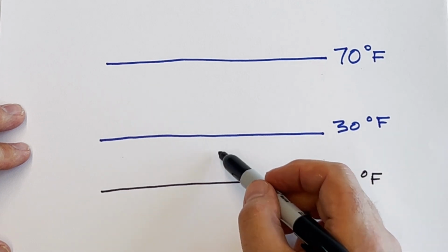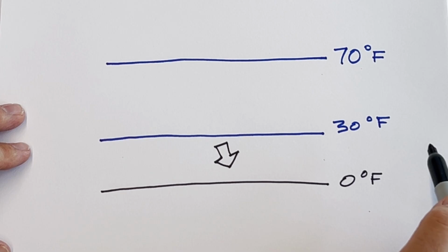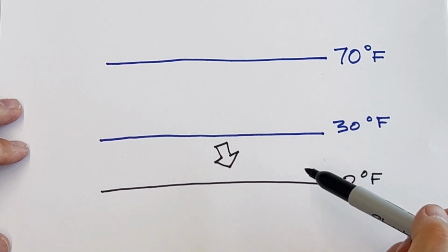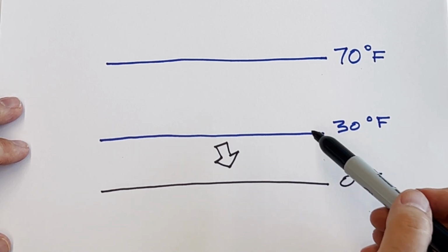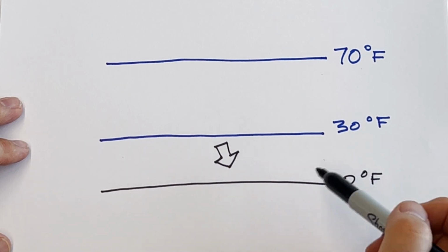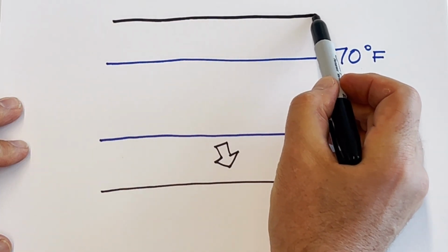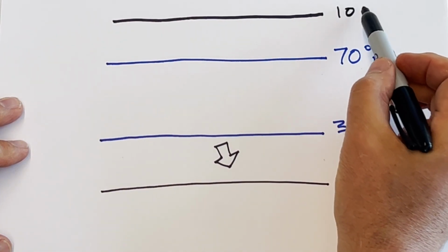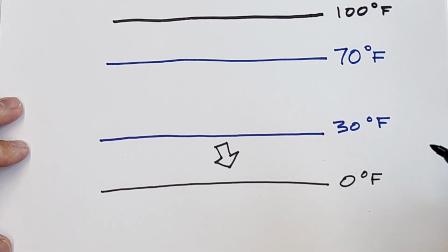And that exchanges heat. It extracts heat from the outside air, and that heat heats that refrigerant. In fact, it evaporates that refrigerant. And the compressor then compresses that low temperature, low pressure refrigerant up to a high pressure and a high temperature. And that might well be 30 degrees hotter than the indoor air.